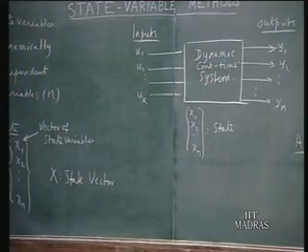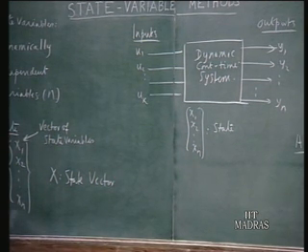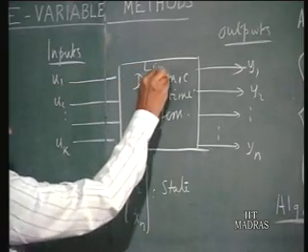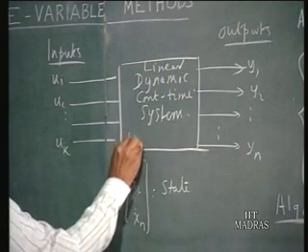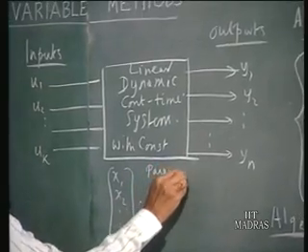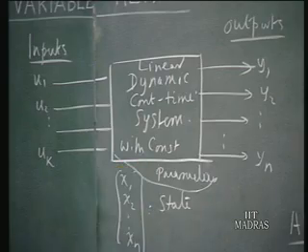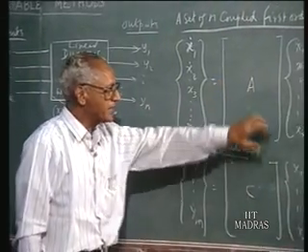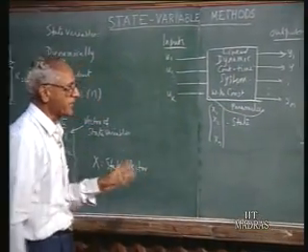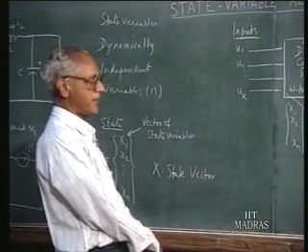Now if the system happens to be linear, and we assume the system is linear here in this example already, and furthermore if it is a constant parameter system, so I will say linear dynamic system with constant parameters. If the system parameters are constant, that is a time invariant system, the entries in A, B, C and D also turn out to be pure constants, pure numbers. They are not functions of t or anything. So A, B, C, D are matrices of constant numbers.